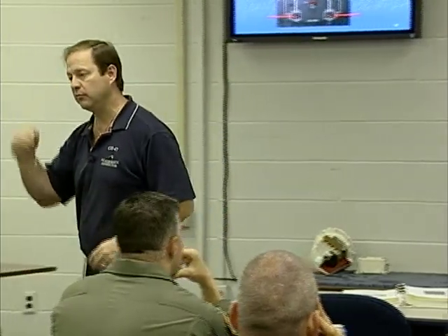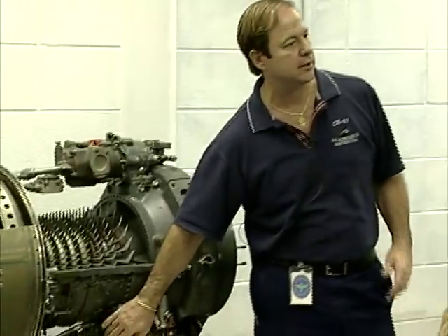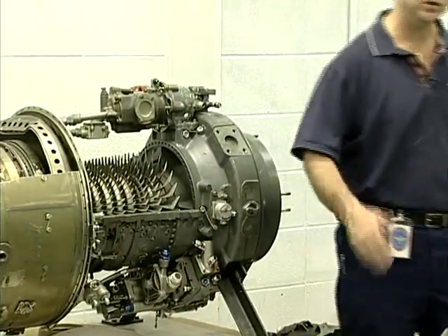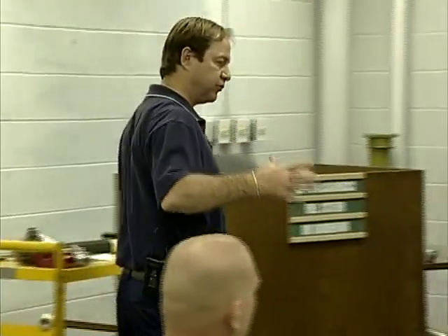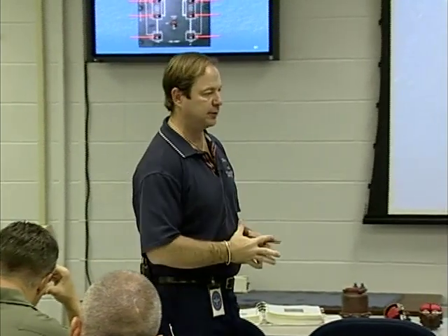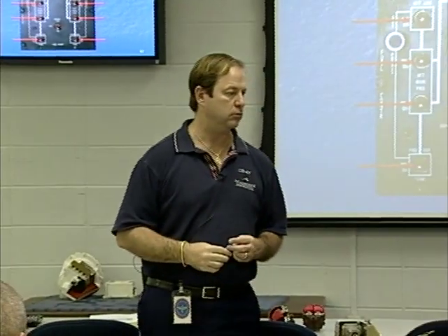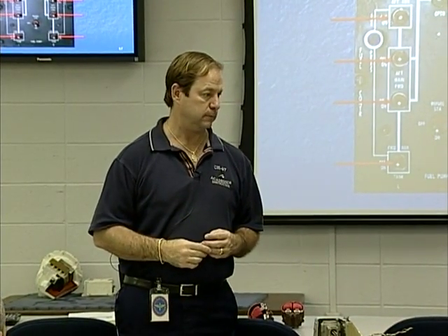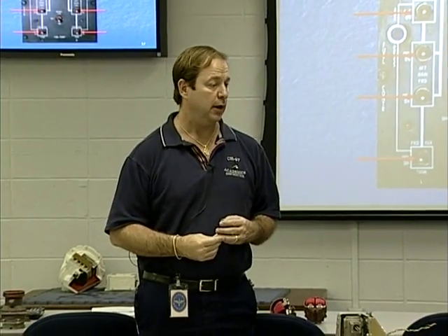Reality is we don't need them, so why do we turn them on? It just puts less wear and tear on these engine-driven fuel pumps, making them more reliable for when we do need them. So we're pressure fueling up to the engine-driven fuel pump, and from there we've already talked about the process. So all the pumps are working at one time if all the switches are on? Yes, sir. It's a constant process.